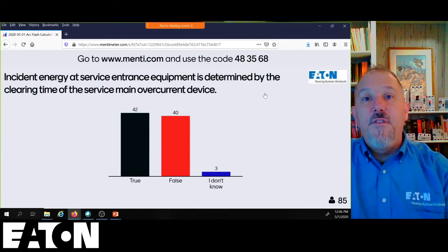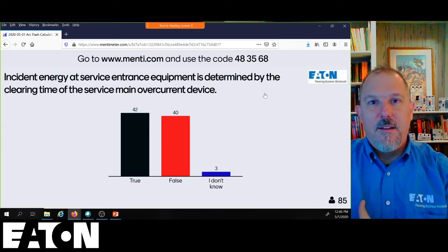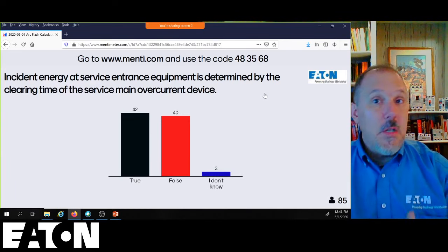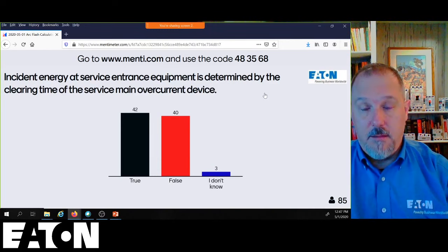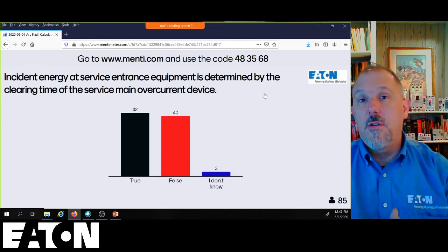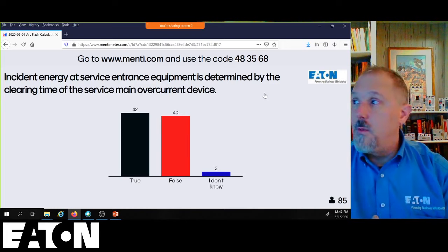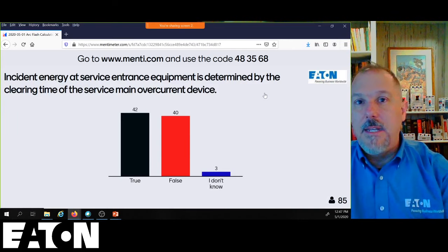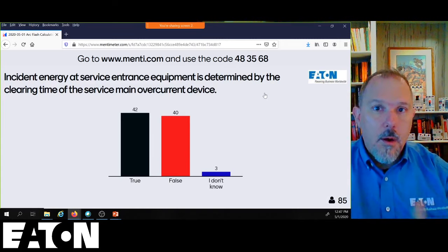I'm at 1.25 minimum, probably, on my transformer size for that line side overcurrent protective device, and I have an intentional delay. That fuse is not going to limit the amount of time that arcing current can occur inside of that panel board. And we have to make a decision. Do we use a 2-second rule? Do I actually give the calculation for however many seconds it takes and get this huge number that I can't design to or work on?